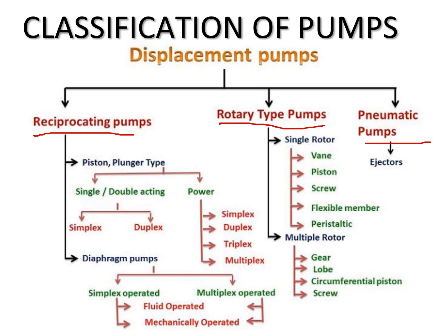For the piston, plunger or diaphragm pump type, you can simply imagine. We have a video at the end of these slides. It is nothing but like an injection. How the injection works, that is what a reciprocating piston or plunger type or diaphragm pump does. That is how it functions. For diaphragm pumps, we can say it is like the blood flow in our heart, the human heart. That is how a diaphragm pump likely operates. In this section, it is segregated into single acting, double acting, power, simplex, duplex, and so on. The principle still stays the same. Only the operation differs.